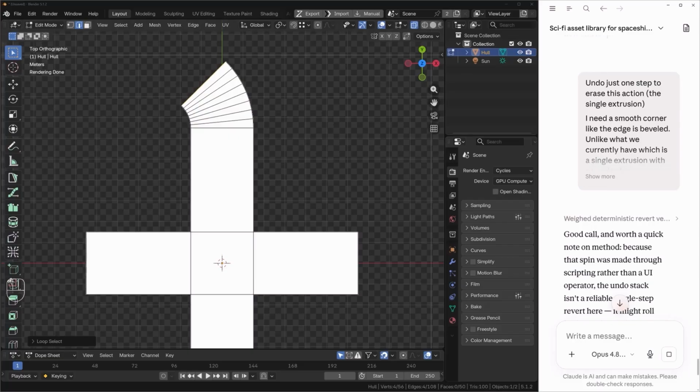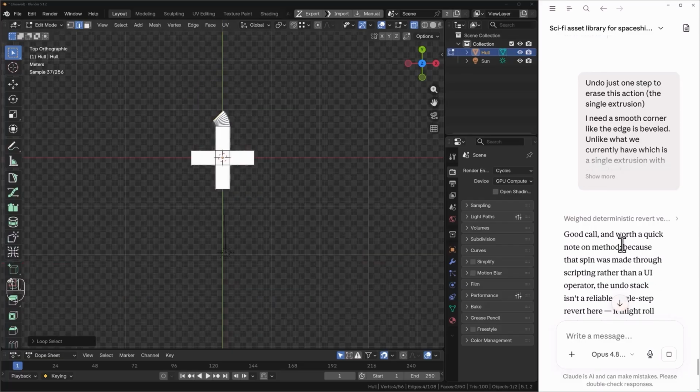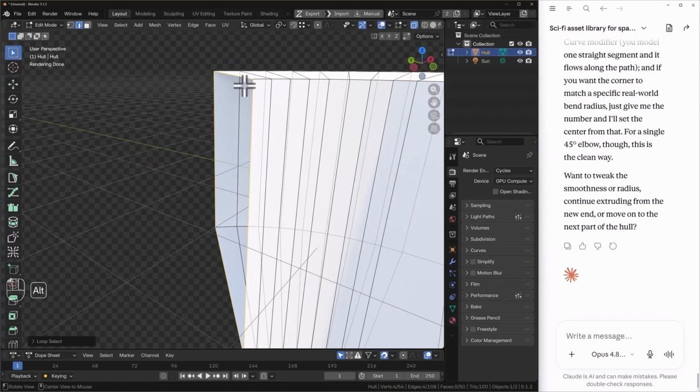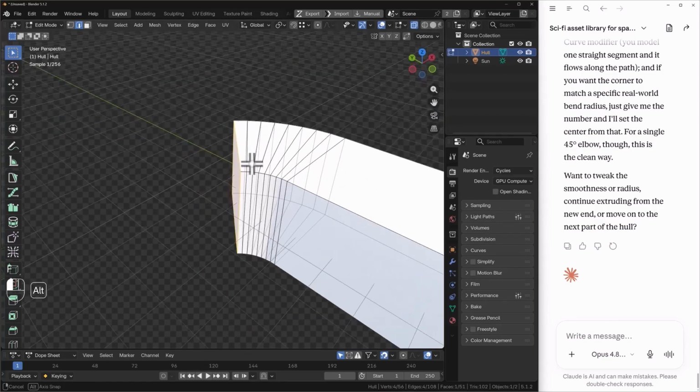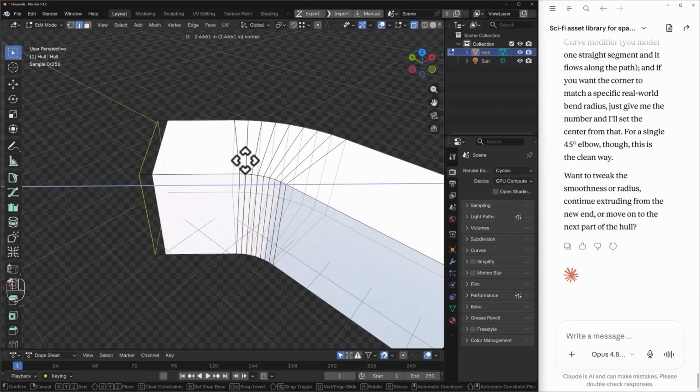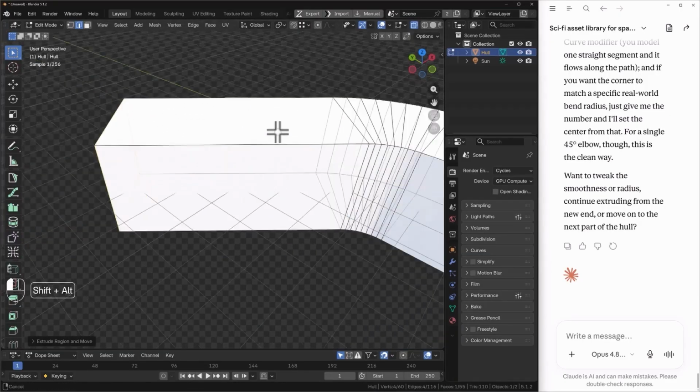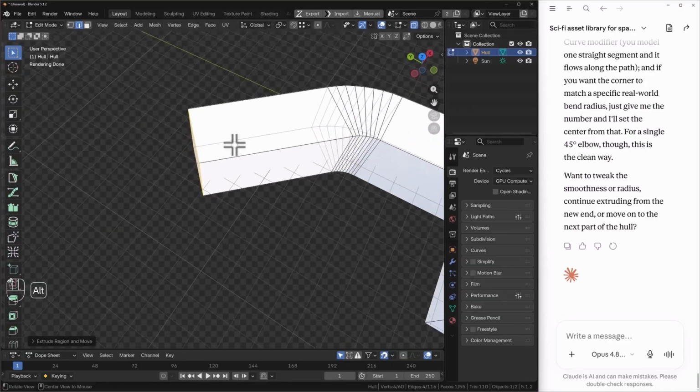This is a very fine result. This is what we're going for. See it? A detailed prompt produces a detailed and very constrained result. It already has this edge loop selected for us. We can press F to close it. Now press E to extrude it all the way somewhere there.